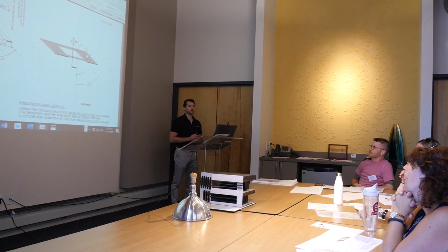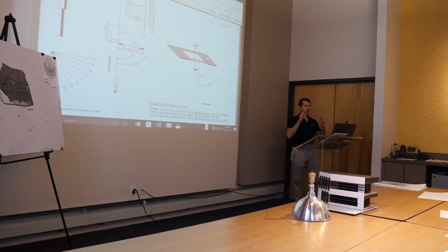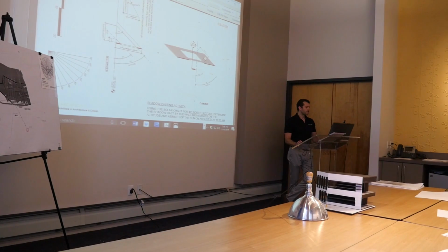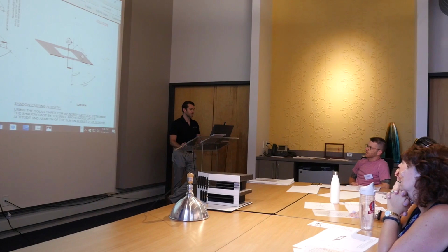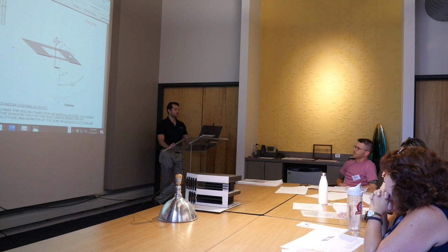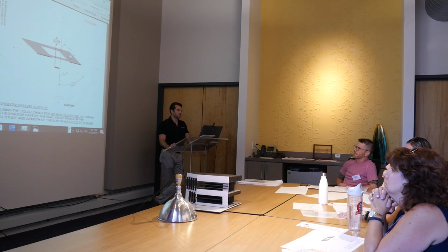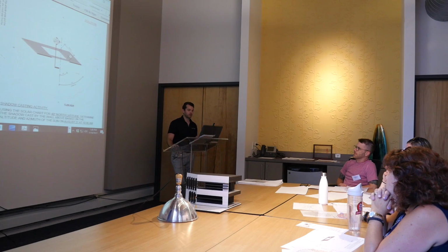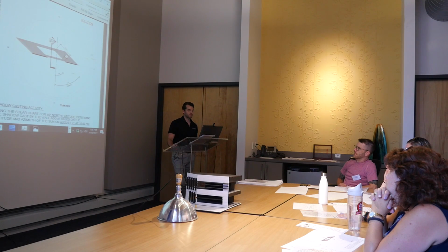For doing a whole building, this takes hours and days to cast all, but it's kind of like doing a coloring book. You just kind of zone out and you just start drafting lines. And it's kind of fun because you can calculate this just using a compass and a protractor, and basically with geometry draft the lines, but you could also use geometry. You've got heights and lengths, and then you can find the angles using trig, essentially, sine, cosine, tangent. So that's kind of the meat and potatoes. That's how they did before computers. You're out there drafting and finding the effects on the shadows.